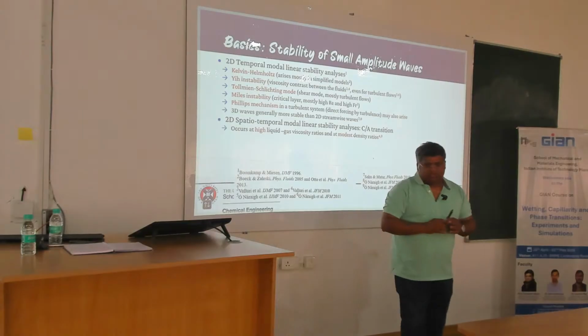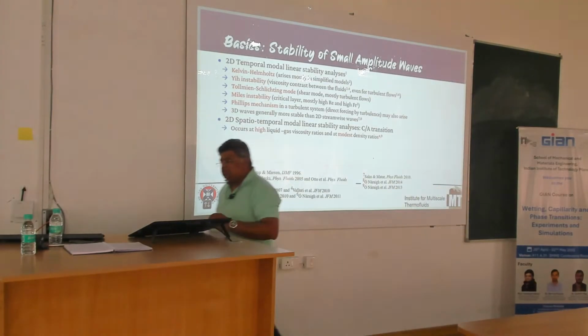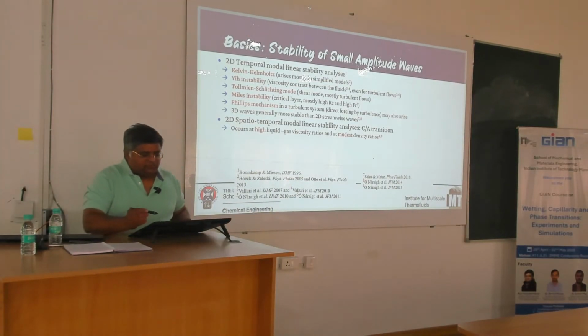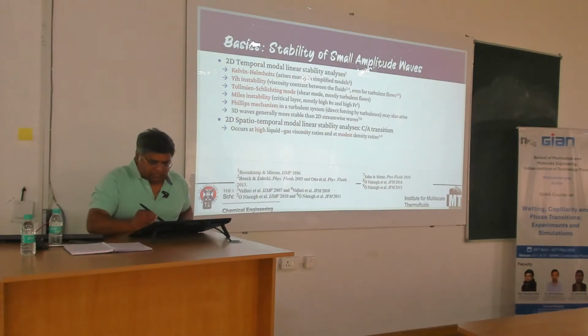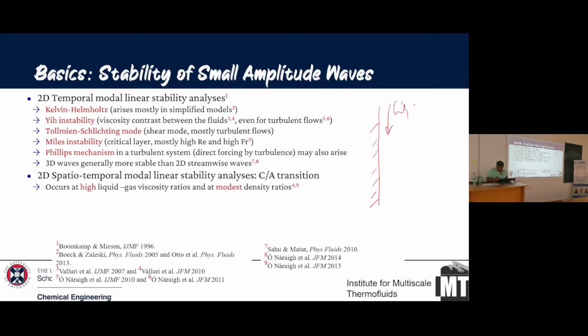But in some cases, if you are a chemical engineer, you would probably know the condition of flooding. Typically, if you have a distillation column, you've got a liquid flowing down this way, and a gas going up. This is usually used in absorption and distillation columns. Because of the interaction between the two, waves are developed, but the gas is going in the opposite way to the liquid.